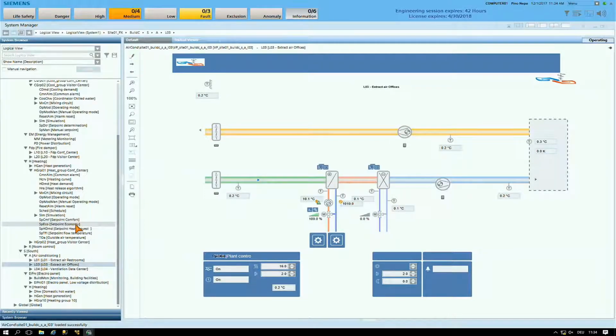Yeah. Pino, if I look at this, if this was a standard PX with a standard library used, would it be recommended that you could just create the graphics new automatically using the standard graphics generator, and then maybe floor plans, etc., convert across? Would that probably be a good recommendation? Yes. Because I think the question is, if you would use just the headquarter standard library, is it recommended to rebuild the graphics pages by using the Desigo graphic generator? Yes, I would. New graphics, yeah.